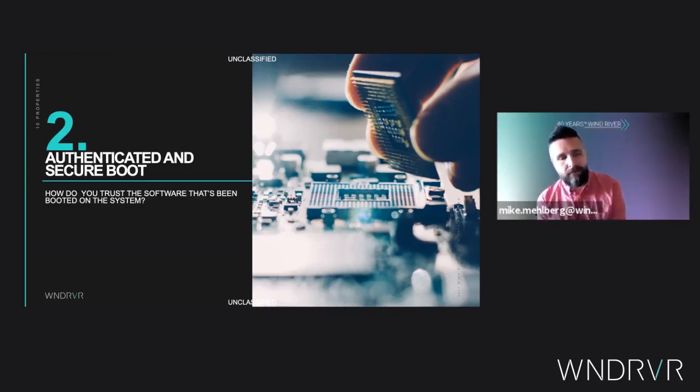To protect against that type of attack, things like boot kits and root kits you may have heard of, you need an authenticated and secure boot. You essentially want to make sure that as you boot up, you're checking your environment, you're making sure that you're not on a lab bench somewhere, that you are in fact running on the system that you intend to run on. Then from there, you extract your keys from some kind of a hardware root of trust, maybe a TPM, maybe an HSM, maybe an FPGA. It doesn't really matter where. That's going to depend on your threat vectors.